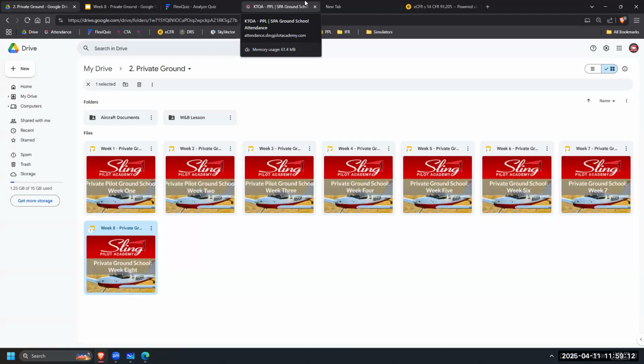Yeah. All right, unless it's getting worse, right? Electrical fire can also lead to real fire, and that's why you try to avoid it. So how would you squawk an emergency code if you had everything off? I mean, it's serious, but fly the plane first. Main thing is to fly the plane. If you turn everything off, you cannot stop anything. Now you don't have a transponder, but the priority is really to be safe and not to get any worse.